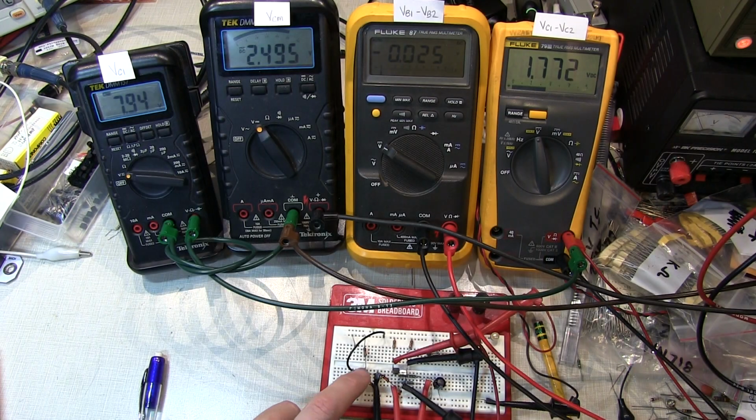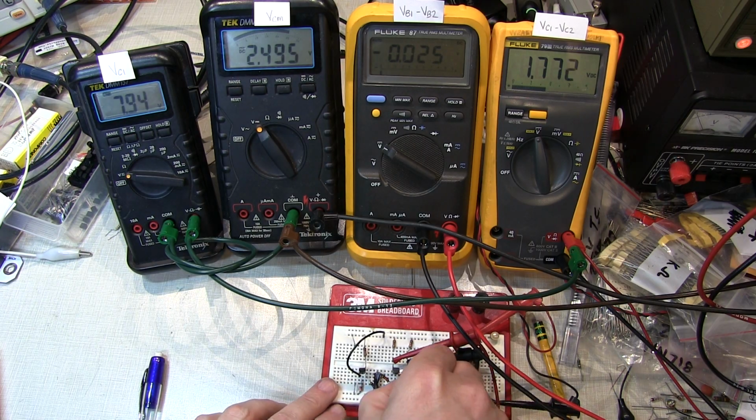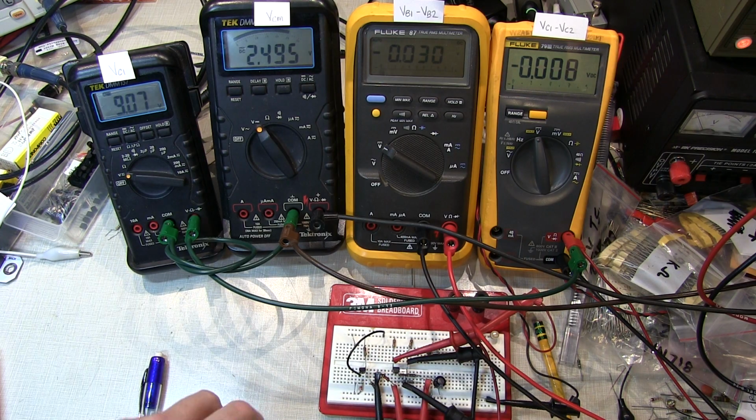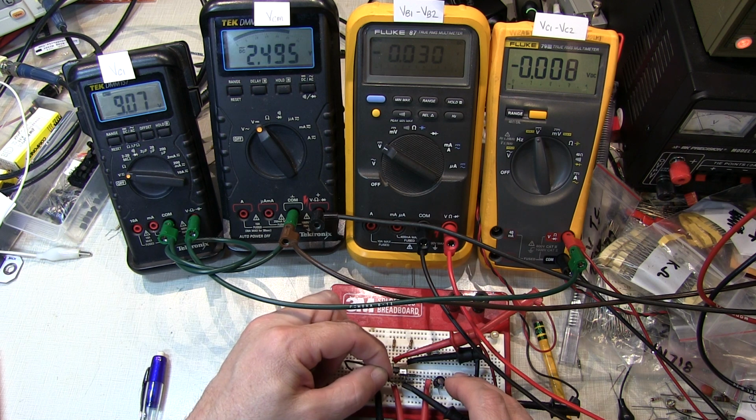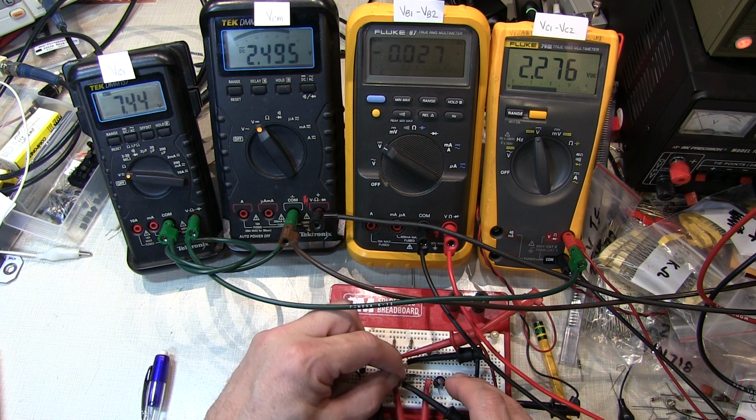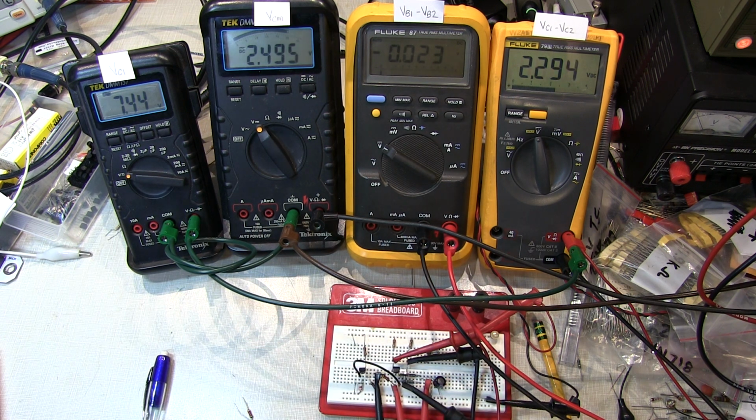Okay, so I still have a simple current source set up here as I showed in the schematic from the previous set of videos. So what I'll do is I'm going to remove my little 2.2K tail resistor and take the output of my current source and tie that into the coupled emitters here to bias up the circuit.